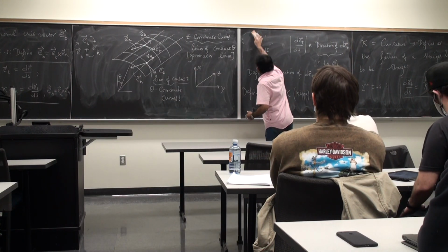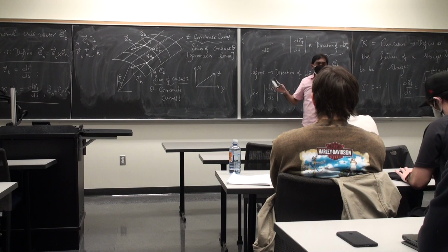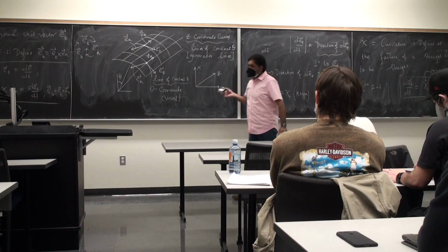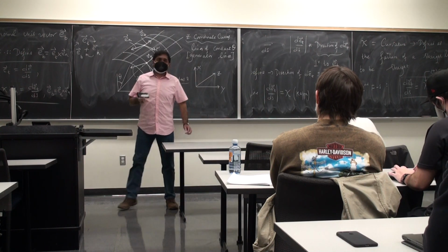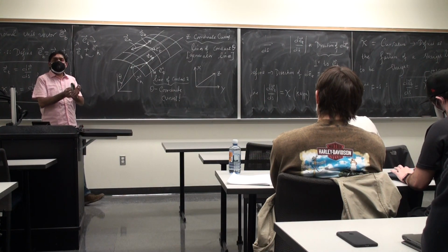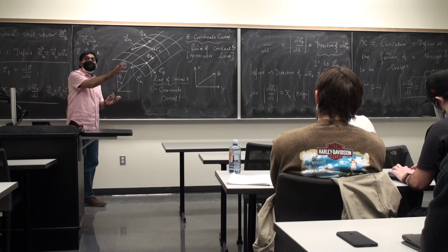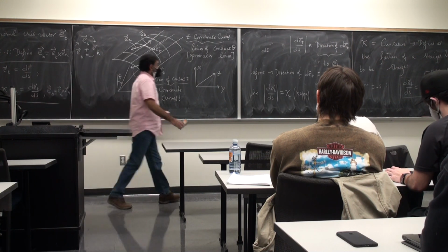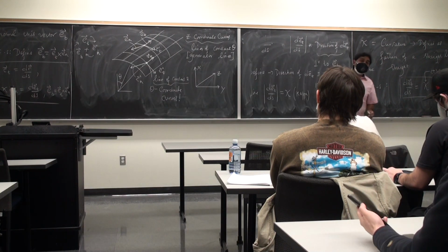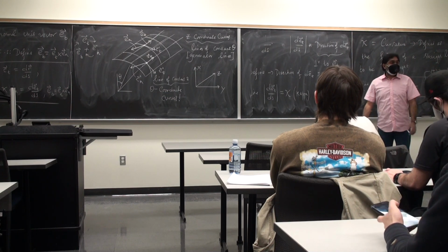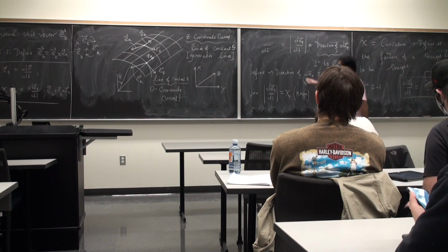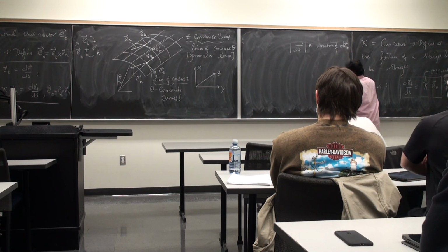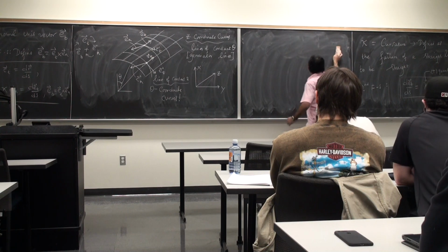I'm going to go forward. Any questions, please? In deformable body mechanics, this is a curvilinear coordinate system, and it is called a convected curvilinear coordinate system because it is convected along with the body and deforms along with the body. These are an integral element of understanding strain, finite strain deformations, finite rotations, and so on.